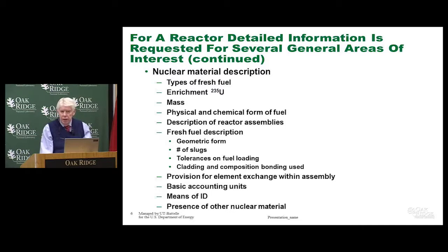And what is the cladding made out of? Is it stainless steel? Is it zircaloy, aluminum? What kind of cladding does the fuel have? And what is the composition? And is the fuel bonded to the cladding? What is the bonding material that one uses? In the case of liquid metal reactors, for instance, some of these have sodium bonding between the fuel itself and the cladding.